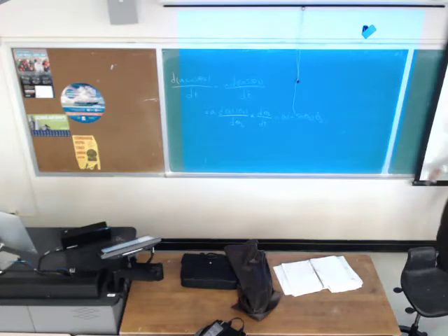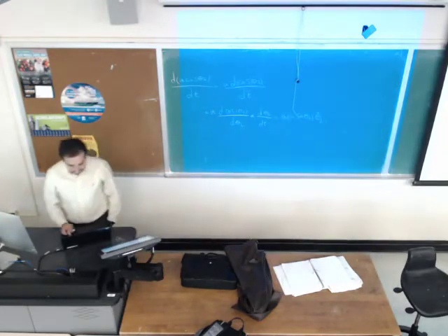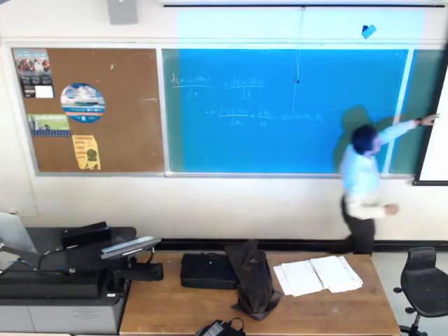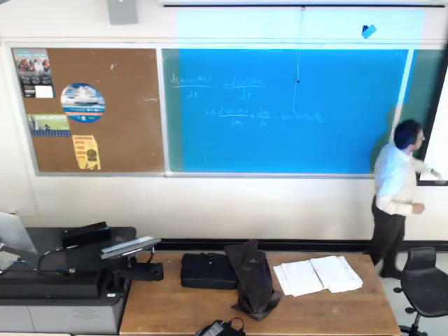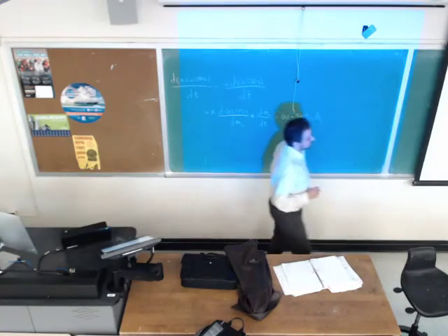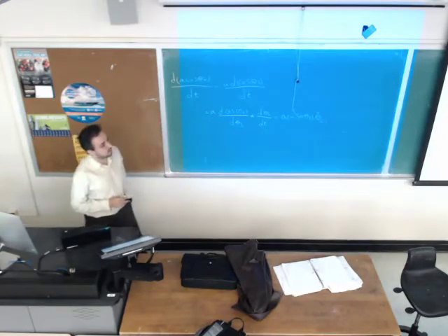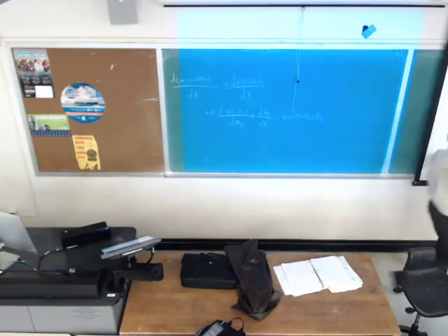So we did that to derive two equations for velocity analysis. We end up with these two equations. The variables were d dot and theta dot 3. I showed you how we can write the equation in matrix form. We move every term with the unknowns to one side, which are d dot and theta dot 3, and move the other term to the right side. Then we form three matrices: matrix A, matrix X, and on the right side matrix B. And for vector X, we are going to have our unknowns, which are d dot and theta dot 3.